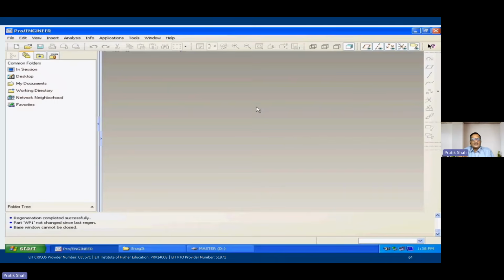So I have done that. I have created a process plan wherein I have shown the tool. It would basically be a single point cutting tool. This is an APT program. And now I am generating the tool path. This is tool path generation.